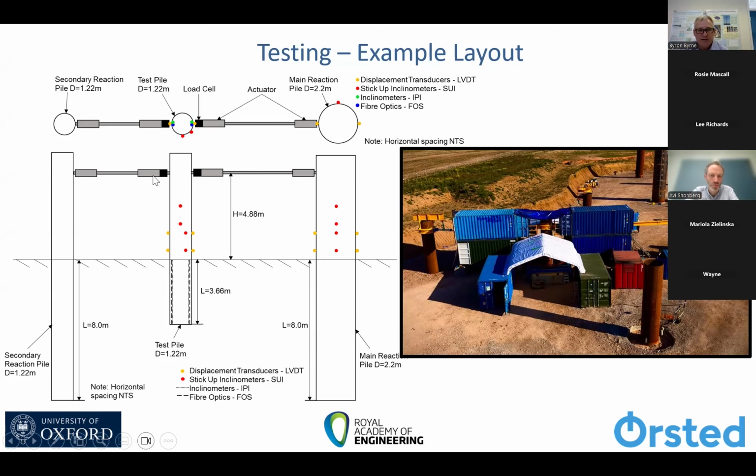Computer controlled actuators allow us to apply any loading to the pile, all load controlled. One-way cycling, two-way cycling, pseudo-random loading, whatever we want. And then at the end of the test, because these reaction piles are much larger, we can pull the pile over to fail it. That's very important. We want to see what is the capacity following the test. You can see lots of shading to make sure that the instrumentation is not affected by the sunlight or rain even.